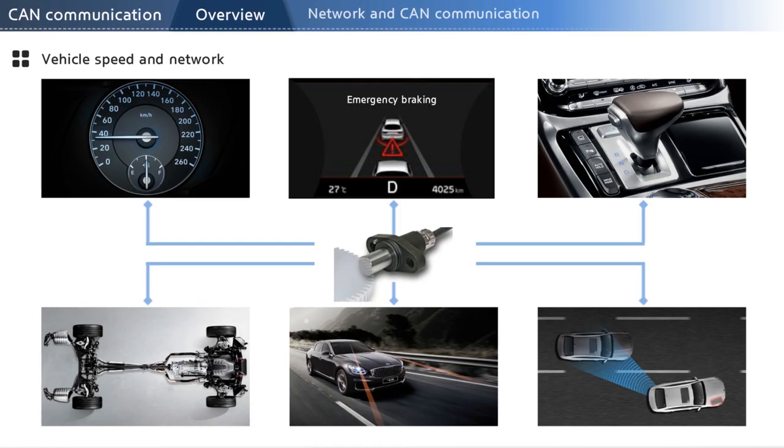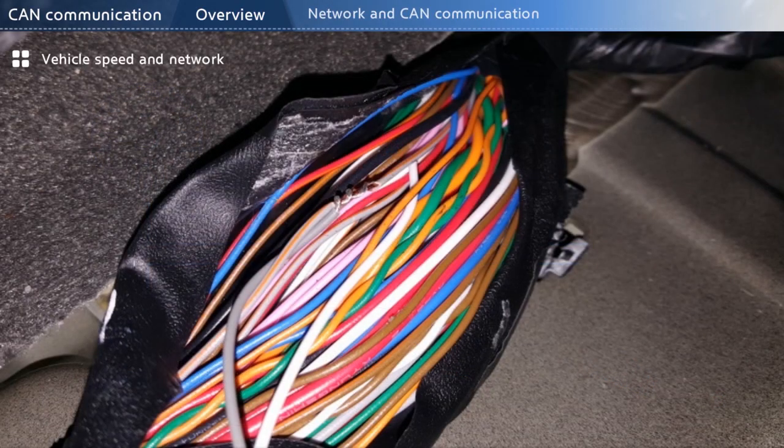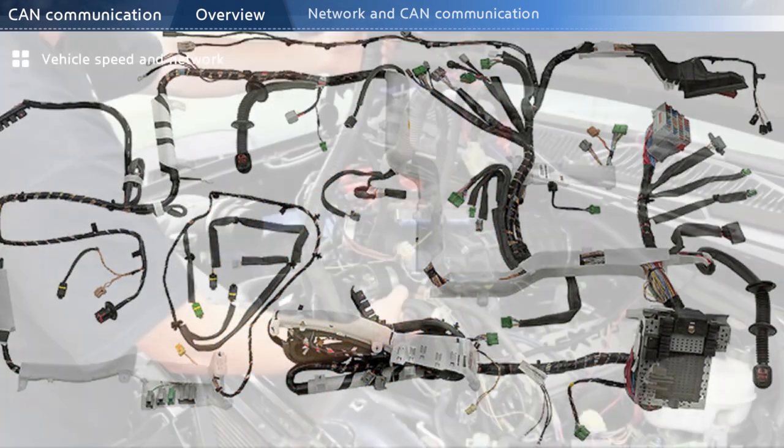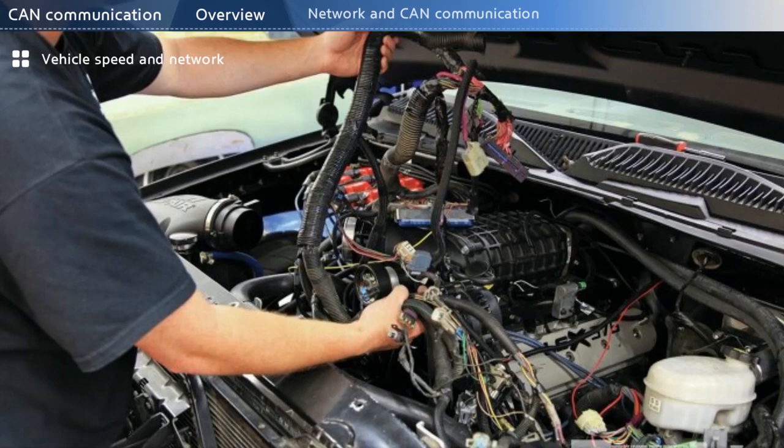Then, why not connect all controllers directly to the speed sensor? Doing so will dramatically increase wiring and the weight of the car as a result. Complex wiring also means an increased risk of faults from poor connection or disconnection.